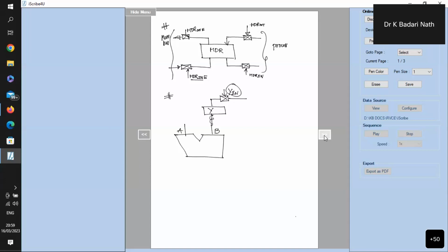It is the other way; it is not to the B, it is to A through a multiplexer. Through a multiplexer it's connected here, and it's connected here. The other input to the multiplexer is the constant 4, and the one control for this is called select. So select is one control signal, and Y in is another control signal. B does not have a control. B is directly connected to the bus. No switches are required. Whenever we place data on the bus, it always comes to the B path. We don't require any control there.